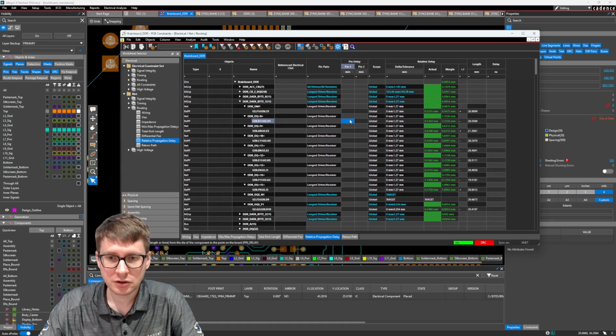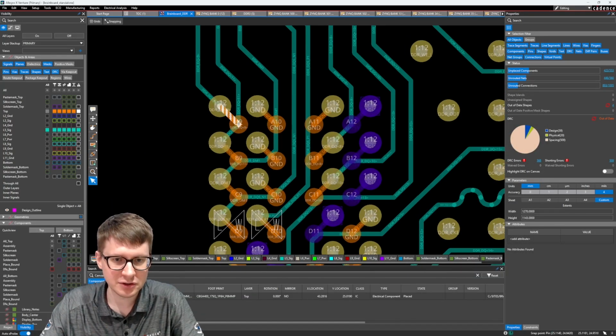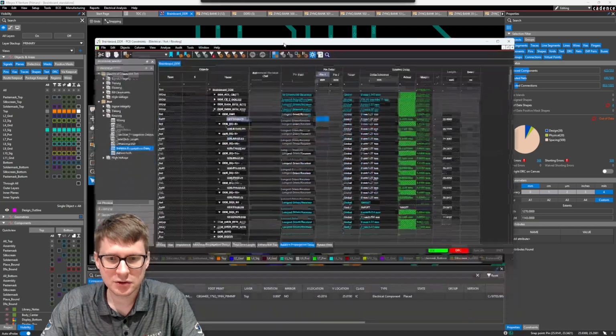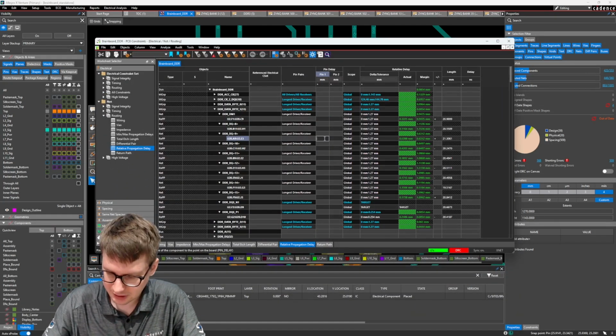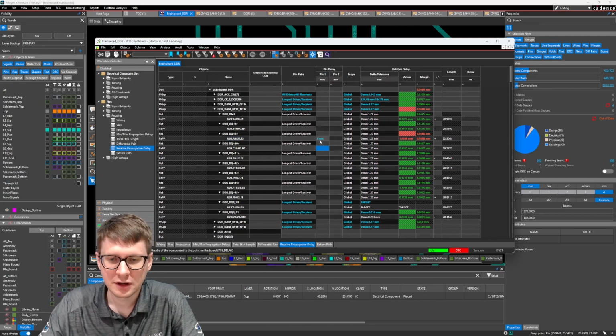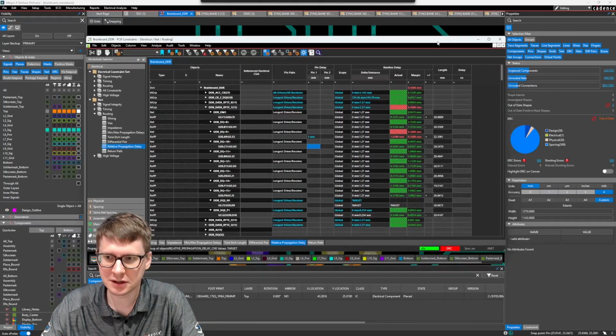Now, you'll notice that in Constraint Manager, you can actually type these in manually. So for example, these are going to be the two nets which I'm concerned about for my example here. So A9 and B9, this is DDR DQ9 and DDR DQ11. Inside of Constraint Manager, I could turn on, for example, a 1 millimeter pin delay on my pin 1, which is coming from U20, that's actually the DDR chip.